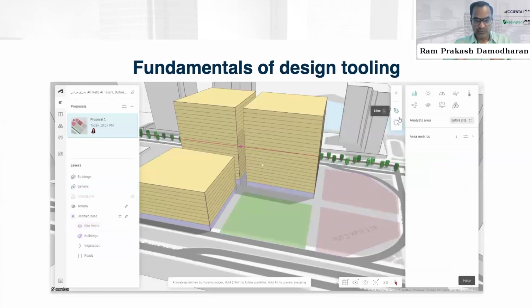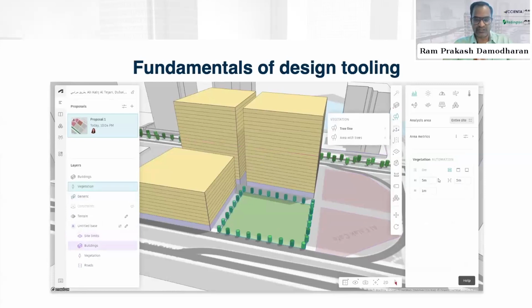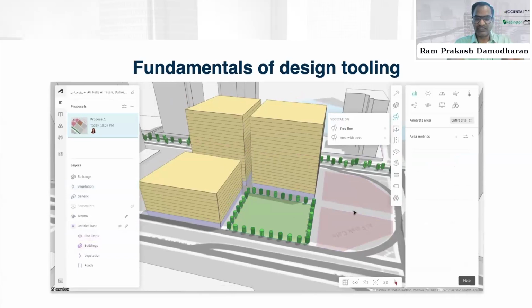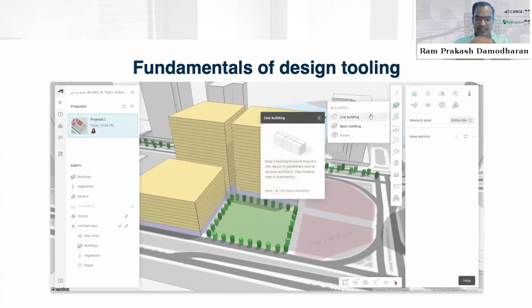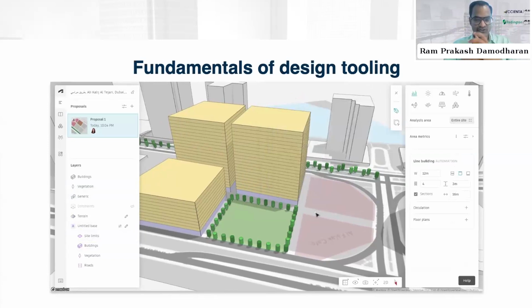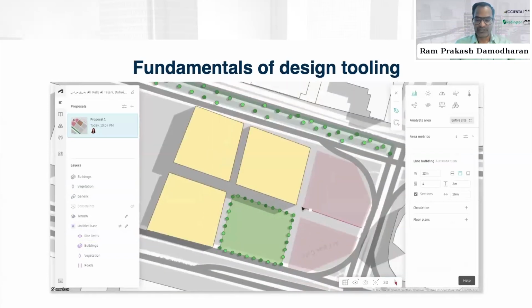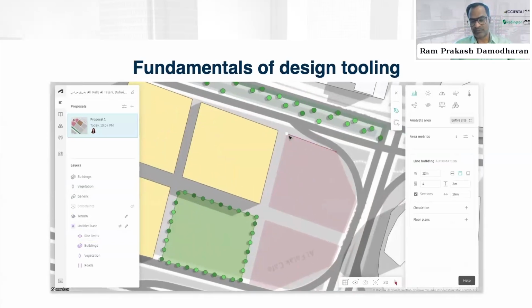You can see the four housing buildings next to each other, and you can also use a site development feature where it can give you options by keeping the parking in the middle of those three towers, and whether the three towers are one single tower divided into different floors. It generates a couple of new designs for you, and you'll love the feature because it saves a lot of time when it comes to space planning, and gives better design options as well.